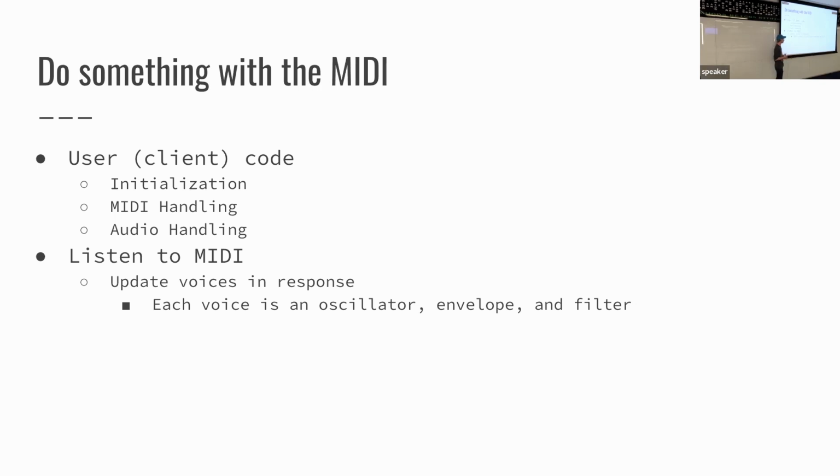if a voice is available, that voice's oscillator will be turned on, and will start what's known as an envelope. If you've got an oscillator that's just doing a signal at full blast all the time, an envelope gets multiplied against it, so that it fades in, and then stays at a certain volume for a while, and then fades out, for however long you set it to, with some filters and whatnot. If there are voices available, we'll start one. If you get a note off message, we'll kill the voice at that particular note.